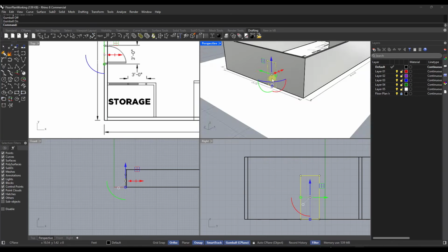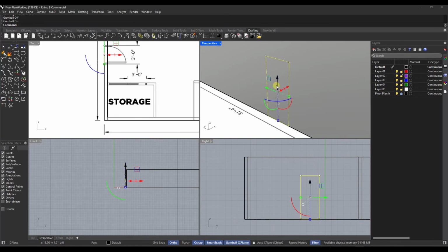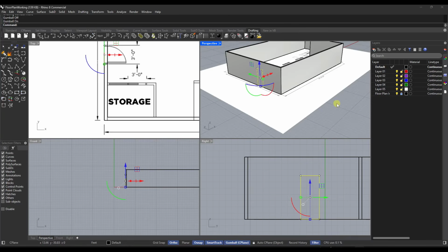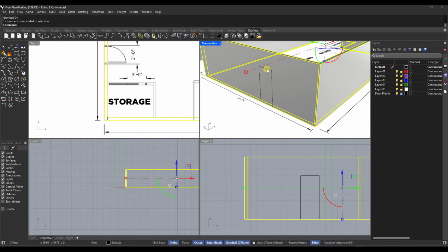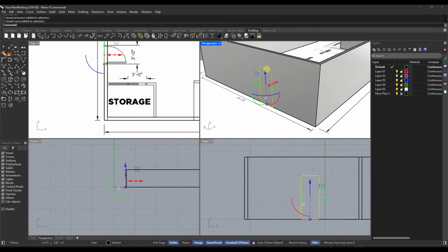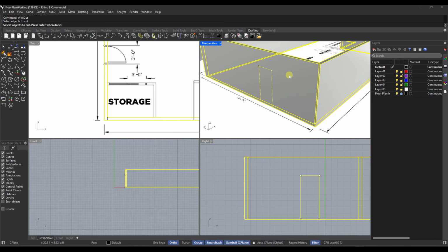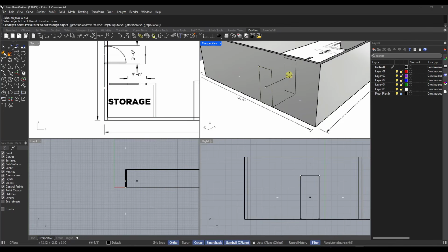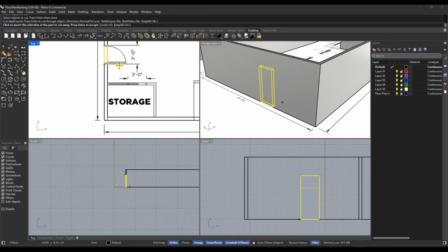And what that's going to do is take this door and it's going to cut an opening in the wall right here. So now I've got this door, or this rectangle, that's blocking out where my door should go. Well, in this case, I want to use a tool called wire cut. So I can type in wire cut, and I've already got my rectangle set, but now it's going to ask me what I want to cut. I'm going to click on my wall, hit the enter key, and move my mouse so that this is past this wall right here in order to cut the opening.